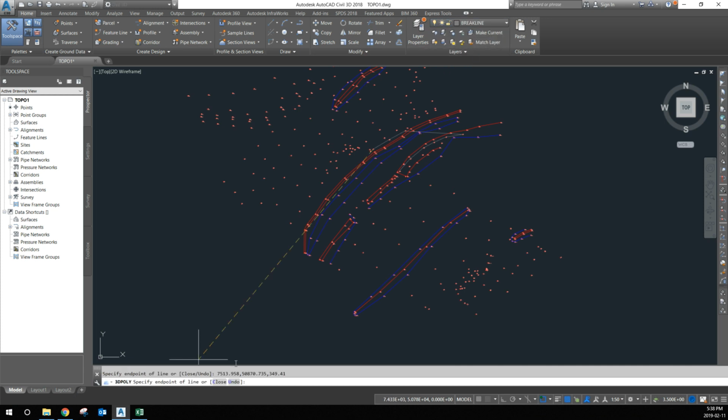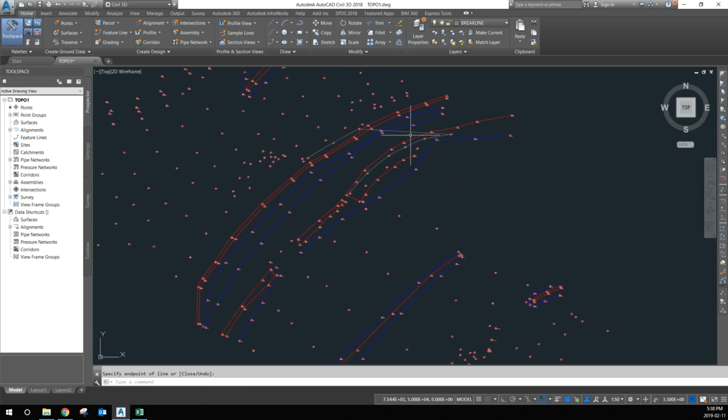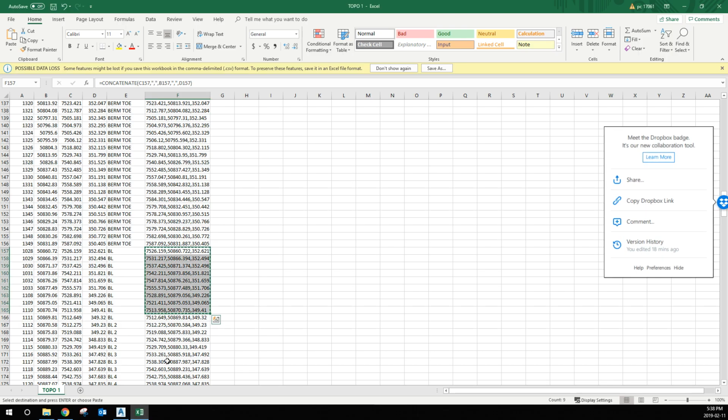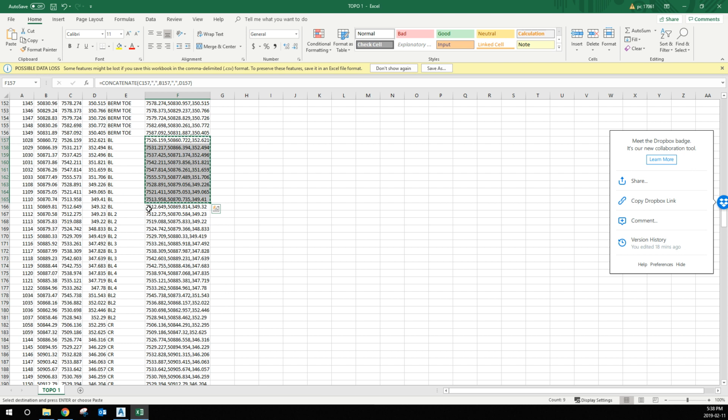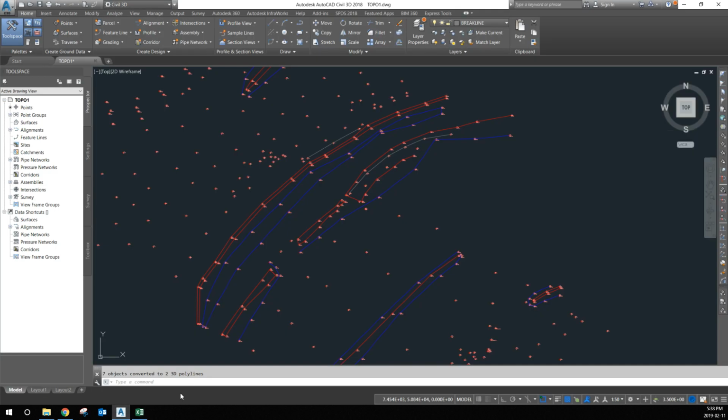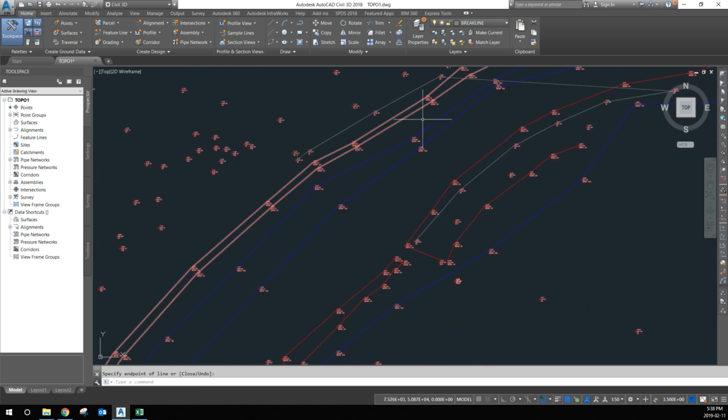Okay, so I'll type in 3P here. Same thing, Control V. See where our break lines are. Kind of explode them here. We know this one doesn't belong, doesn't make sense. Select similar, join, and we're done for those break lines. Check it out again, open our Excel file. Missed one there. Let's try that again. We've got one extra one down here, see?